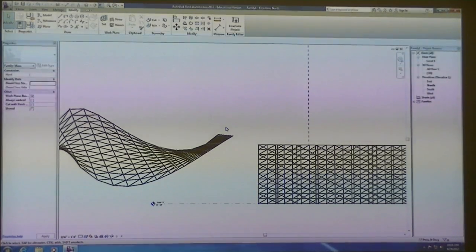Yeah, and to do that, when you go back to the wireframe, just make sure you can actually select that plane. Yeah, do the center and arc, and then change the normalized parameter, so tab over to either 0 or 1. And then move your mouse back off the side. It'll be a circle. Anytime you do any changes on that side, it won't update until you move your mouse off that little box. So click there, and then rotate down, as long as you touch the other side. Right here, yep.